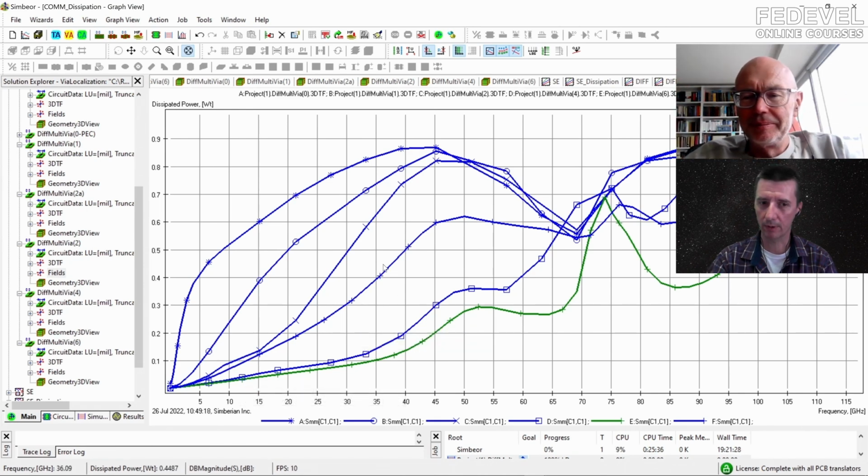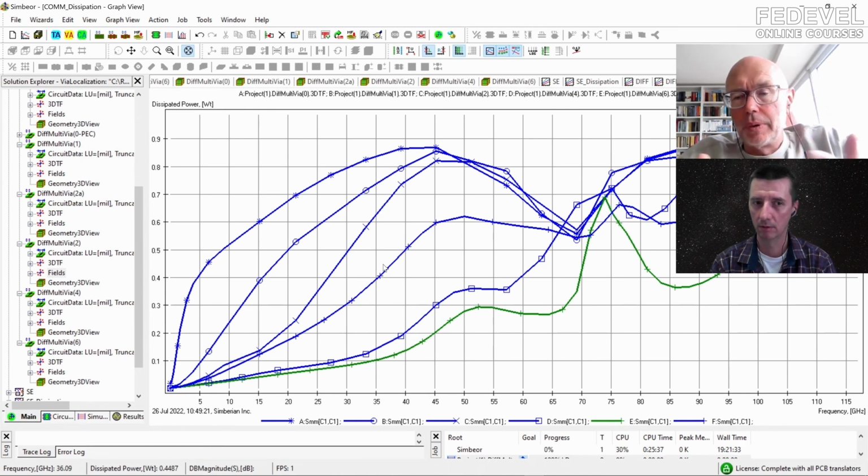So this will happen if you don't do the phase matching? If the edges are not traveling the same length, ideally you launch the differential mode, right? But then if you have turn left, turn right, you have to introduce some compensation structures.